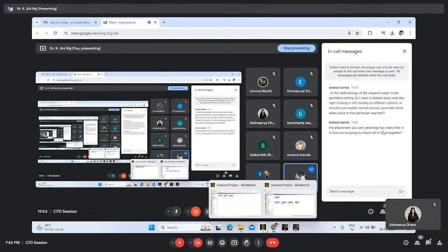You will get total cumulative elements for your mesh in the order of 10 power 5, like 2 lakh, 3 lakh, 4 lakh, 5 lakh. For each element size, you have to check the CL value, CD value, whatever results you are taking.